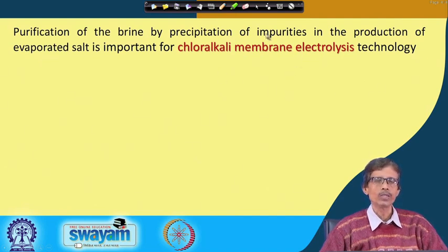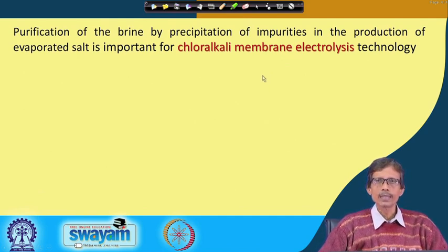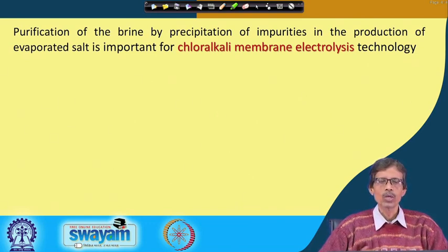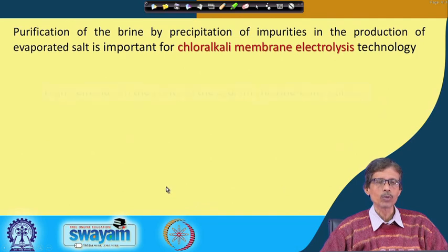So, typically when we introduce a membrane for this particular electrolysis, as we have seen, we can have three components: one is sodium hydroxide, the second is chlorine, and the third is hydrogen. So, you have to separate these three and get all of them individually with not much contamination from the others. The hydrogen gas we intend to get is in pure form, say 90% or 95% purity. It should not be contaminated with the chlorine we produce simultaneously.